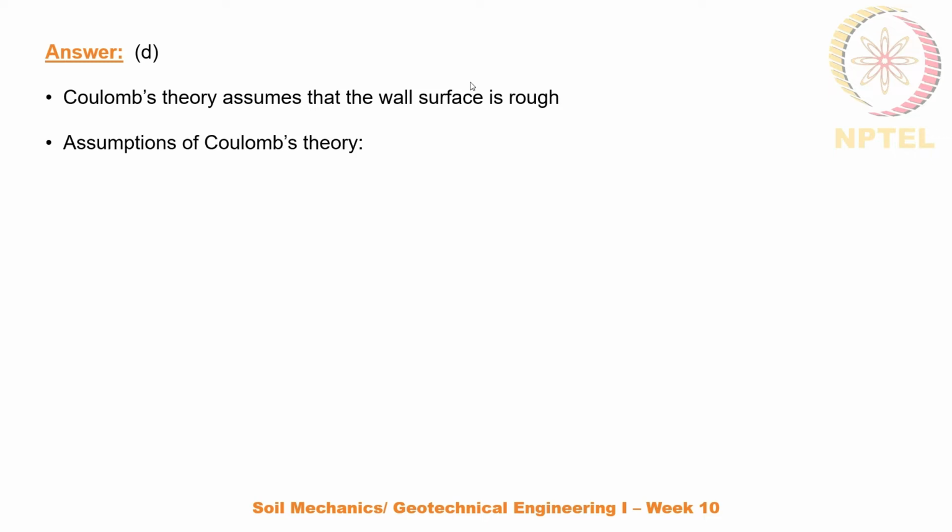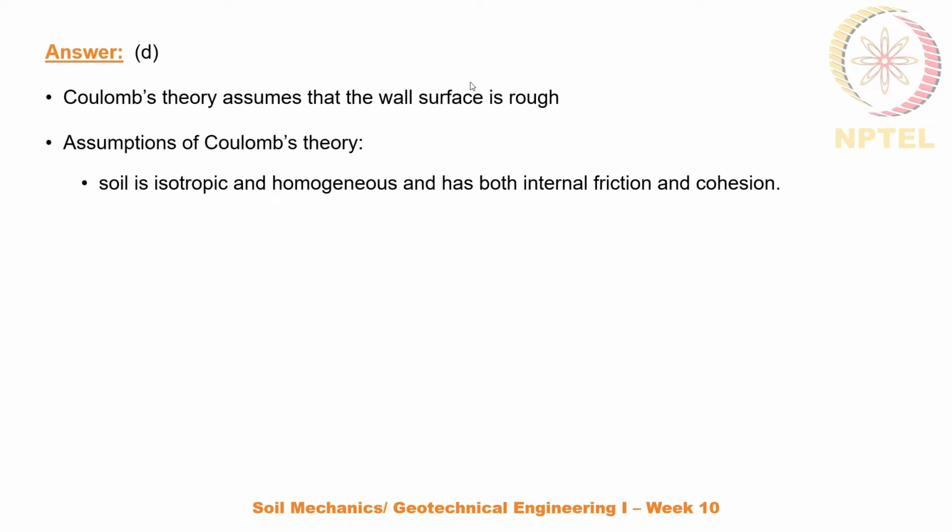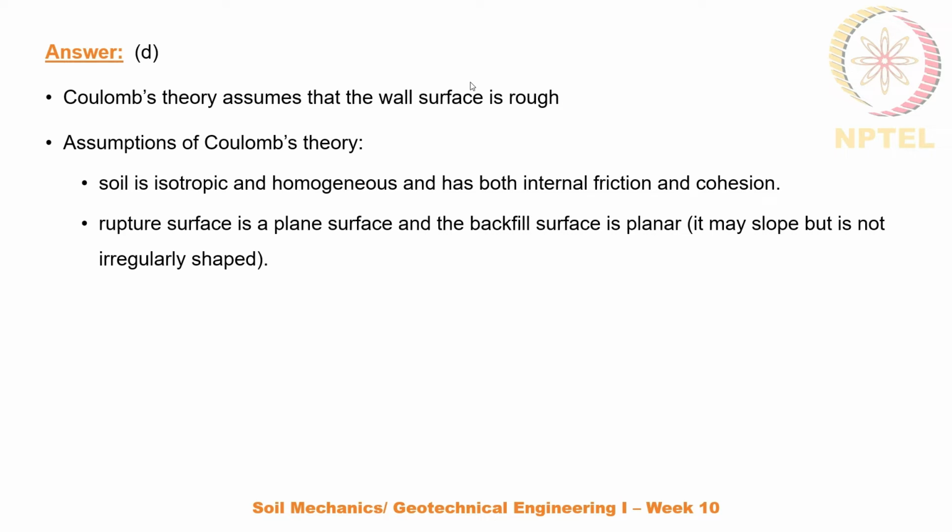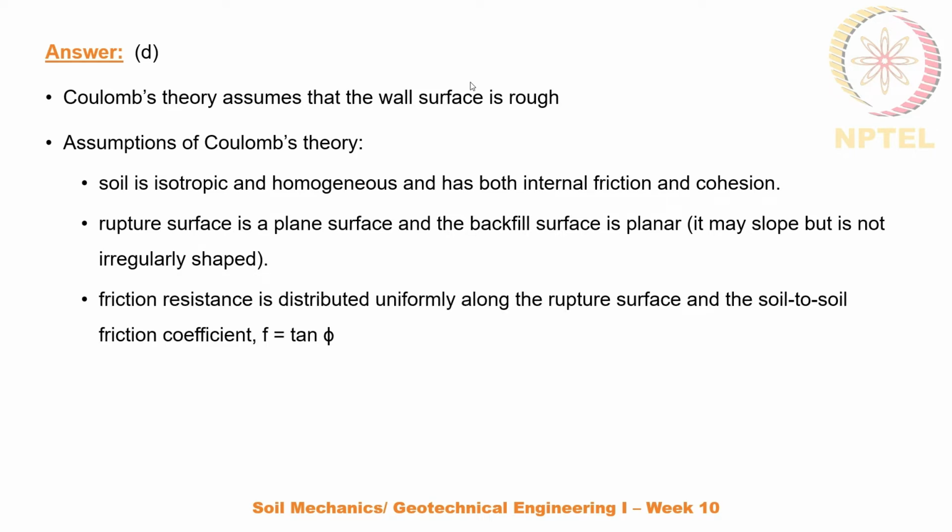Other assumptions of Coulomb's theory are: soil is isotropic, homogeneous, and has both internal friction and cohesion. Rupture surface is a plane surface. Backfill is planar.